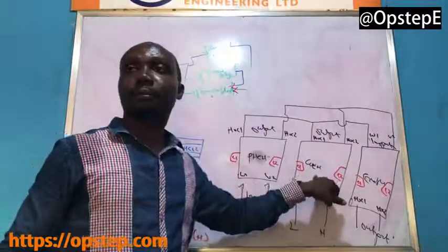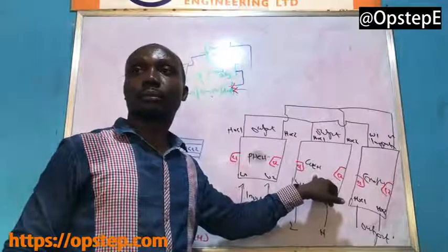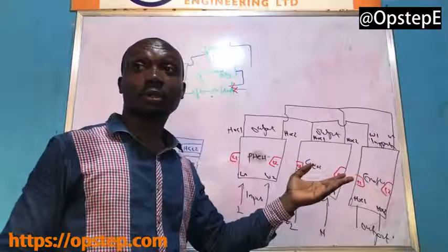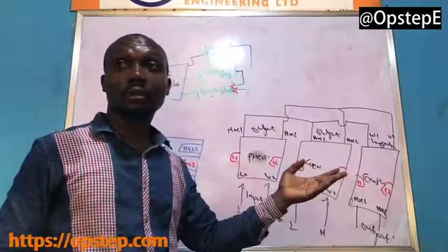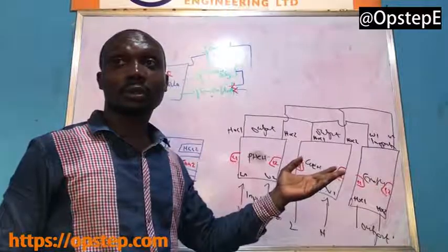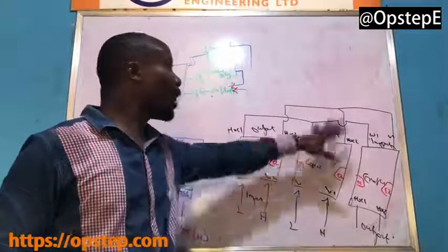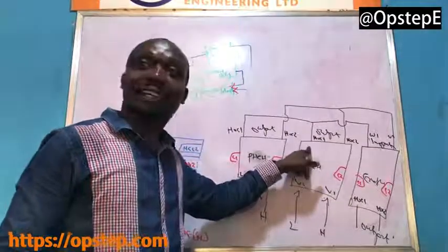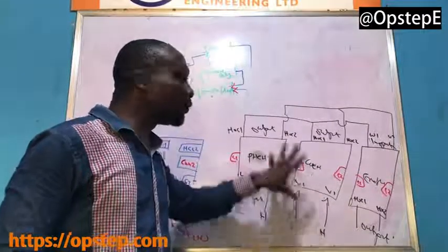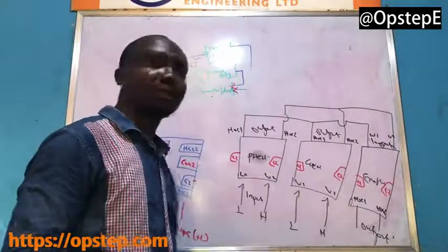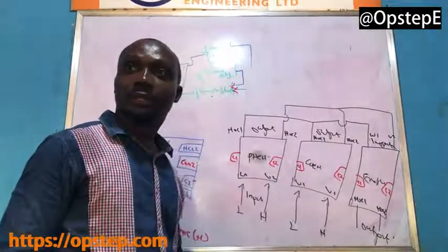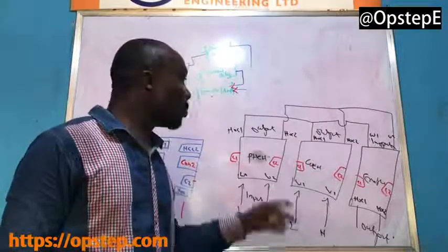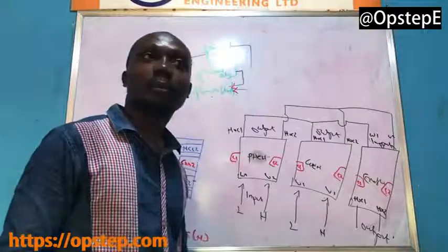You are sending two sources at the same time to the output. Now, you are not actually sending two sources to the output. You are combining them. They are connected together. So your NEPA voltage and generator voltage will jam. The problem is to make sure only one is on at a time.